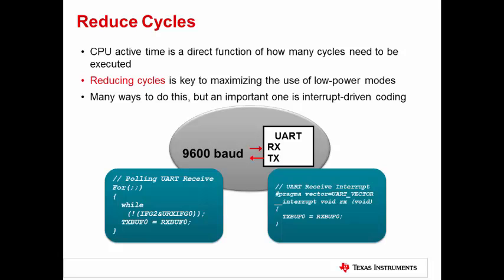This example shows a comparison of a polling-based UART echo compared to an interrupt-based one. Perhaps this example is too obvious, since it shows a difference between a 100% CPU load versus one that is almost 0%. But in many cases the savings are not so obvious and they can be more difficult to implement. But developers should consider them if they can save some cycles.